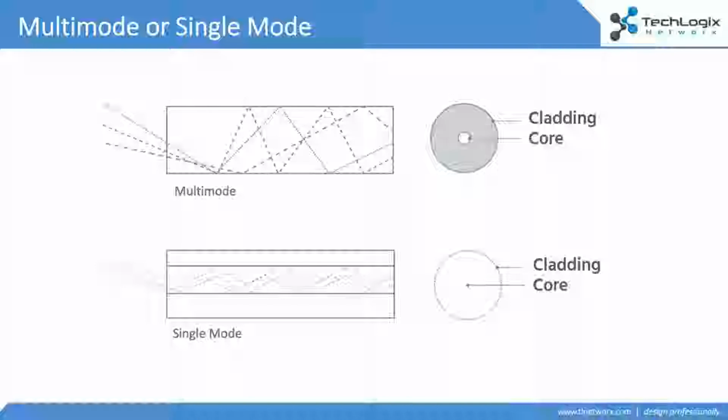So that single mode cable that you're working with, being a smaller piece of glass, keeps those signals in wavelength, in sync, for much longer distances. And this is why that single mode cable with off-the-shelf components will literally push your signals miles, whereas that multi-mode cable, that bigger piece of glass, is a little bit more limited in distance. Now, you can send more signals through that multi-mode cable. You have more bandwidth over the short run to work with, but you are limited to 1,000 feet.